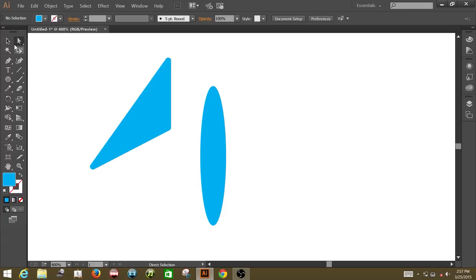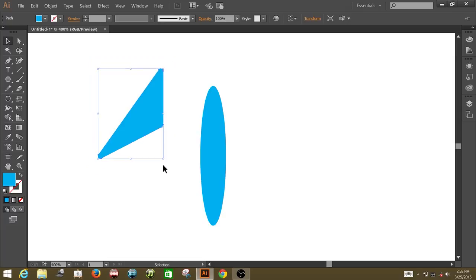Now I'm going to pick up my selection tool. Select this object, come over here to this edge for example, click, hold down Shift and Alt key and downsize it about this much. Release mouse, then keyboard. With my selection tool, I'm going to click and bring it over here. Just a little bit inside here. Right there. It's a good location. Release mouse.